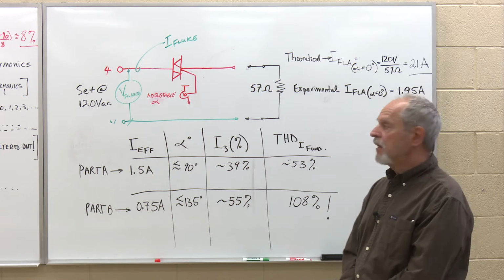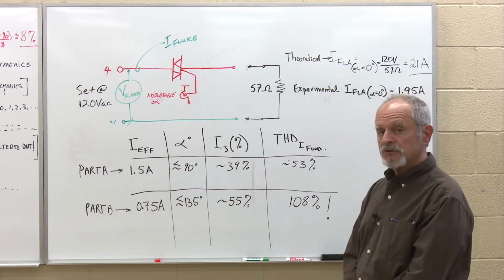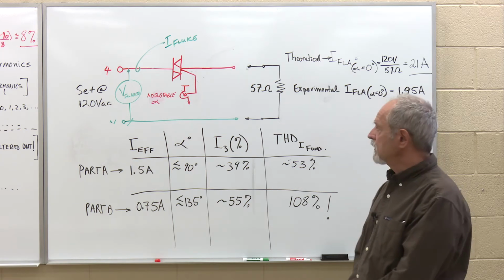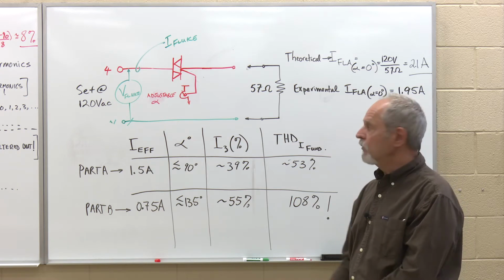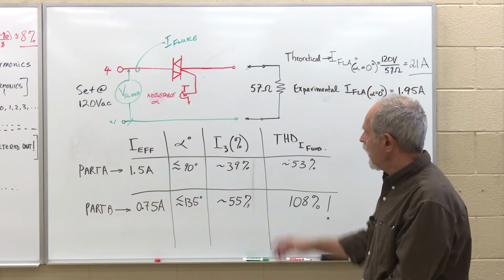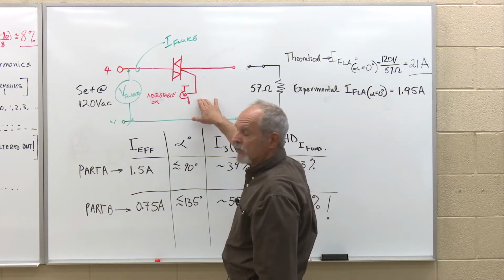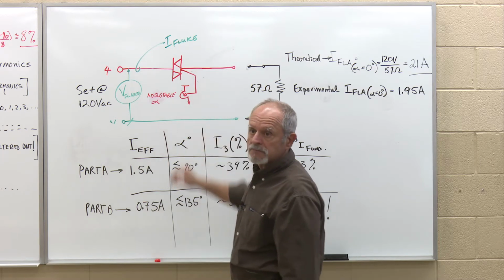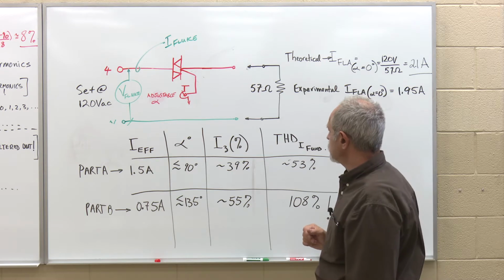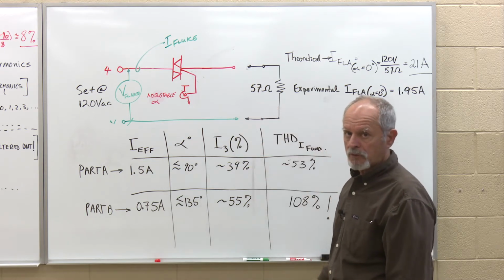In this lab, we're going to look at another switching circuit. This is straight out of Wildi Chapter 30, and we'll be going into this circuit in some detail in our lectures. So what we have here is a switcher you're all very familiar with. It's a TRIAC. We're actually going to use a dimmer switch to adjust the current to a 57 ohm load.